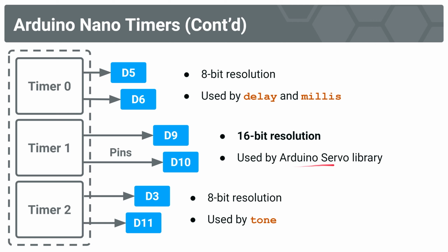And then there's the Arduino Servo library. A servo or servo motor is a component whose angular position you can control through a PWM signal. And so when you send different PWM signals, that changes the position of the servo motor. So if we rely on PWM to set the angular position, then naturally we want a higher resolution signal sent, a signal which can be more precise.